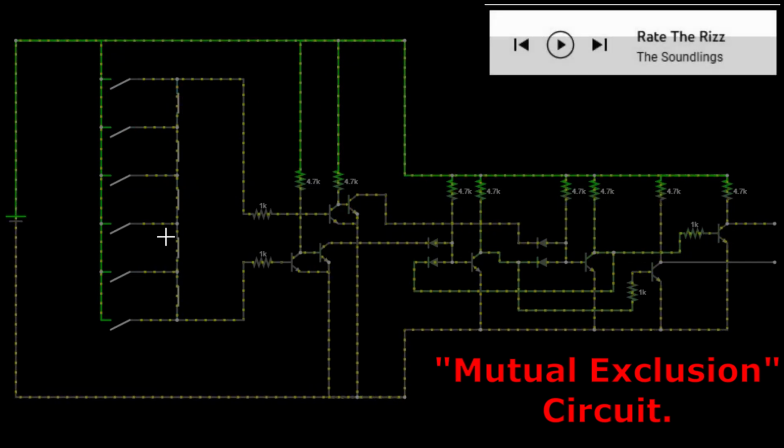This is the motor control logic. The floor selector here, we have the elevator position switches and the actual call switches. These will connect to obviously the SR flip-flop circuits for the call switches. So these can both be on at the same time if there are calls in both directions, but the motor should never be on at the same time for both directions.